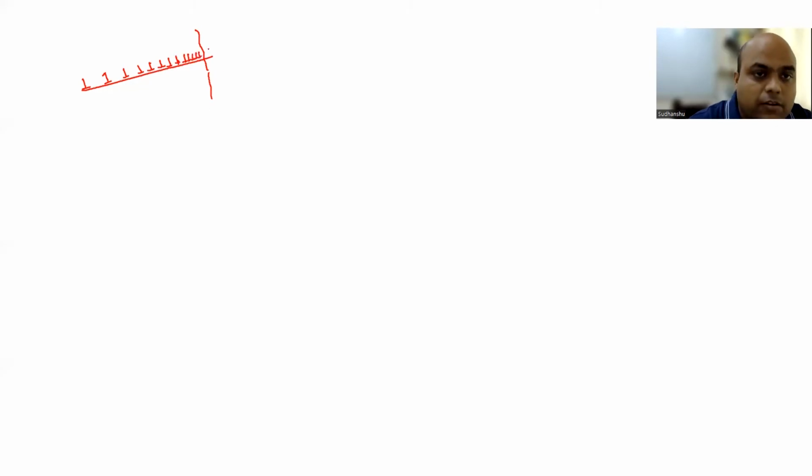You have now a sufficient number of dislocations here. They are getting squeezed in these locations, right? So now you are generating a crack. Call it wedge crack.